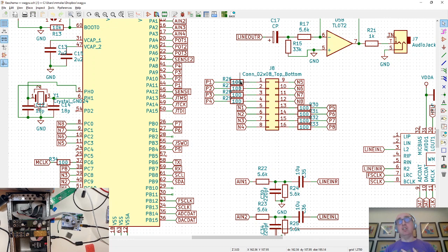And I didn't actually read the datasheet right, so I labeled these positive and negative instead of anode and cathode, because I always get anode and cathode confused. So it turns out I still got it wrong, and I got positive backwards. So to make the LED light, you actually need to drive P low and N high, like an idiot.